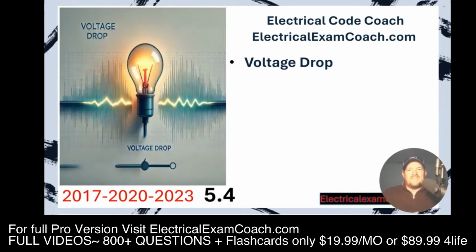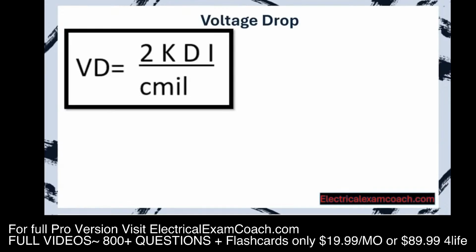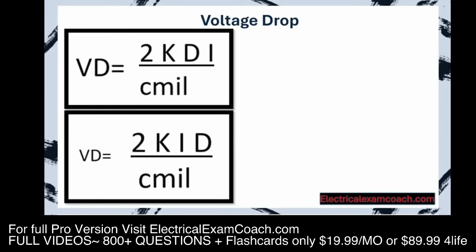Let's get to it. If you were to do an internet search for a voltage drop formula, you would likely find this one right here: voltage drop equals 2kDI over C mil. And that is an excellent formula, and it's actually the one that I use. But I've rearranged it so it's easier to remember. I do it like this: 2KID over C mil. Easy to remember and easy to plug in.